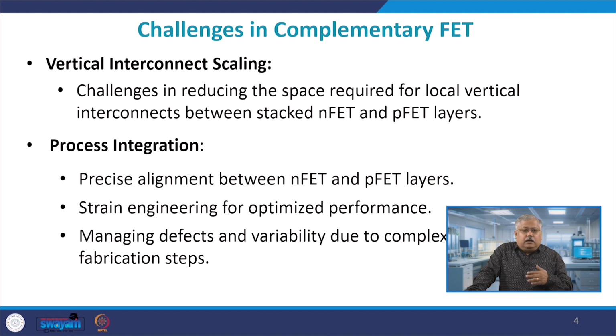They are relatively more complicated as compared to a bulk device or a planar device, because first of all you need to ensure that the steps which we take are precise, and we need to also align the NFET PFET in case of a sequential CFET, and therefore managing the defects and the variability due to complex fabrication steps is also a major challenge in a complementary FET.